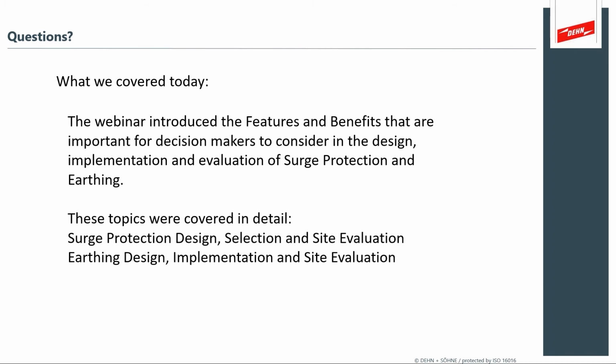Yes, and remember, if you also have grounded control systems, you can have problems with referencing if you have severed grounding connections as well. And like you say, a gap in the equipotential bonding scheme, like you've just mentioned, Mark.